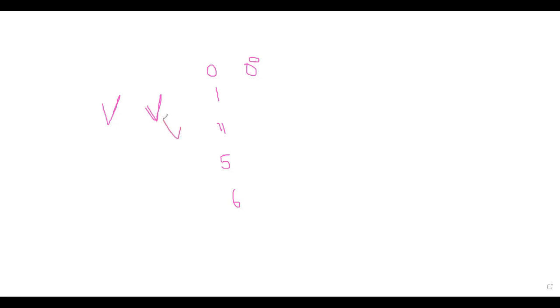If it is in this way, right? 11 o'clock, the upper one, and this is the one you can always see. This is the phase reference. Similarly, for all the clock positions, this digit refers to the angle which is lagging or leading from the reference vector. Generally, we consider the high voltage vector as the reference vector in the vector drawings.